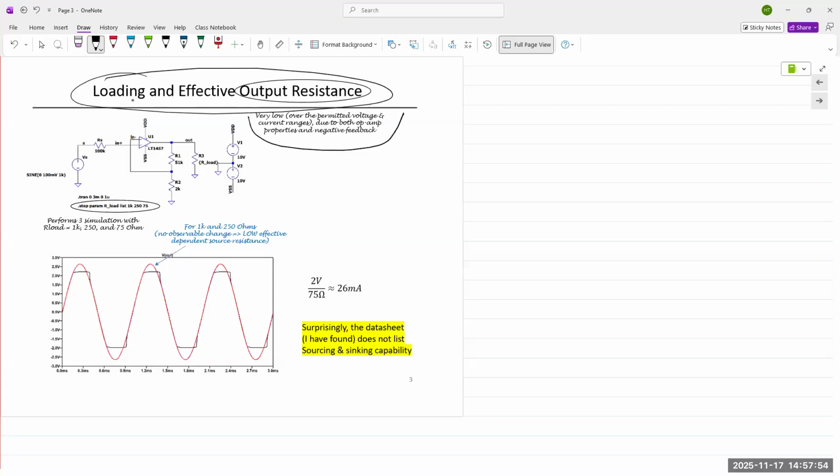There's one thing I wanted to talk about, which is the dot step parameter. And dot step allows us to change the values of parameters that are present in an LT-SPICE simulation. So in LT-SPICE, we define a component, and then we use the dot step param command, which is right here, to specify different values that need to be stepped for that component.